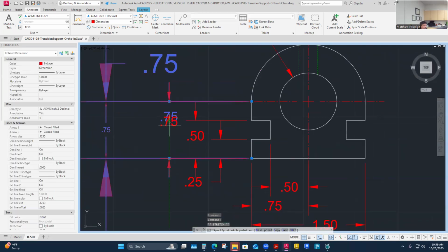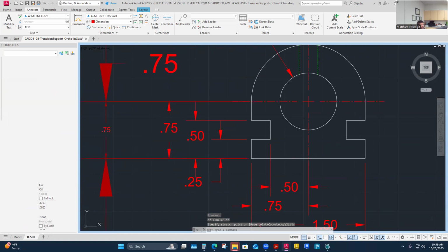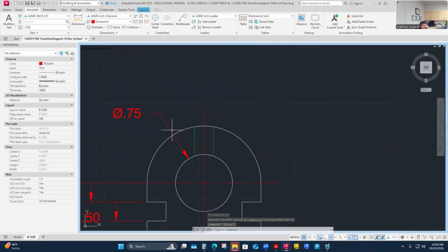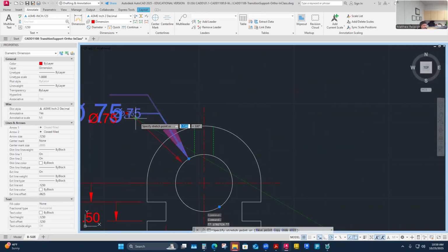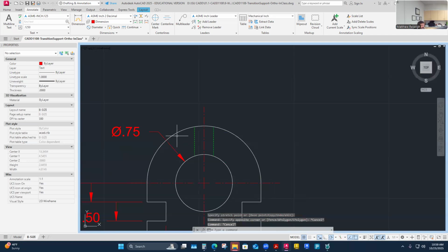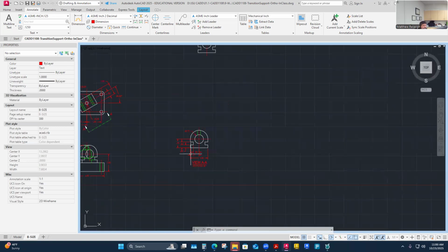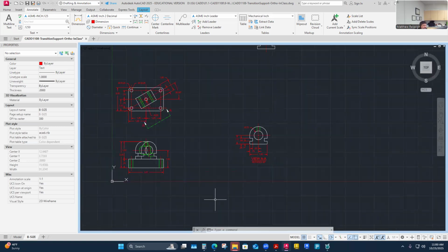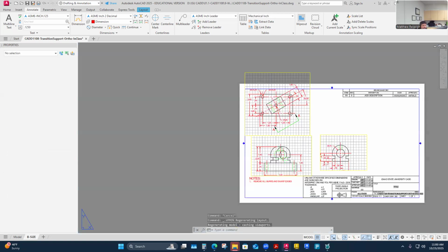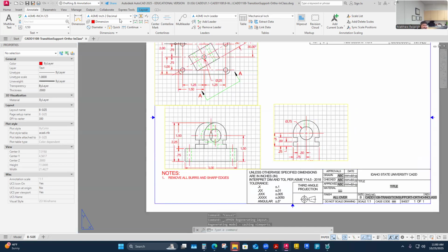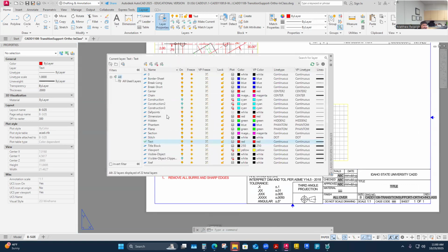If I drop this in, I'll get the lines. Maybe I like this. Maybe I like that okay. It's arguable, but this one I'm going to bring in just a little closer, tuck this in. Those leader lines should be 30, 45, somewhere around there, just not 90 and not 180. All right, that's viewport work. Sheesh, never ends. Yeah, it's kind of hard to dial these in. I've got to do some orthographic alignment, so I definitely need a layer to do that.